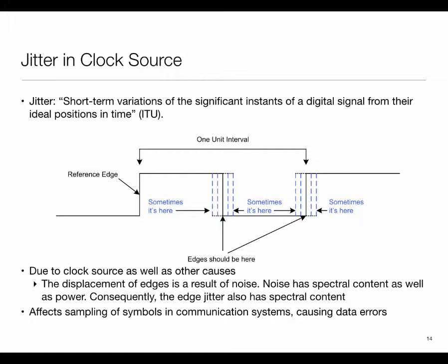Any guesses on how much delay a typical UART, like when you communicate with something over a serial link, how much delay do you see? Are they nanosecond, microsecond, millisecond, seconds? Thoughts? Yeah, tens of milliseconds, hundreds of milliseconds. Yeah, I mean, it could be as much as 100 milliseconds. Okay, so essentially you have a 50 nanosecond or something like that accurate clock, but you're talking to it using a serial link, which has 100 millisecond type latencies and is highly variable, tens of milliseconds variation, depending upon what the state of the buffer was at the time you were talking. Even more, even lower, whatever.